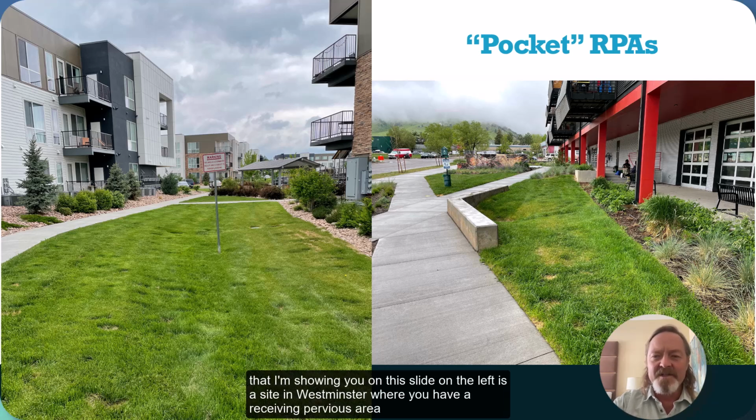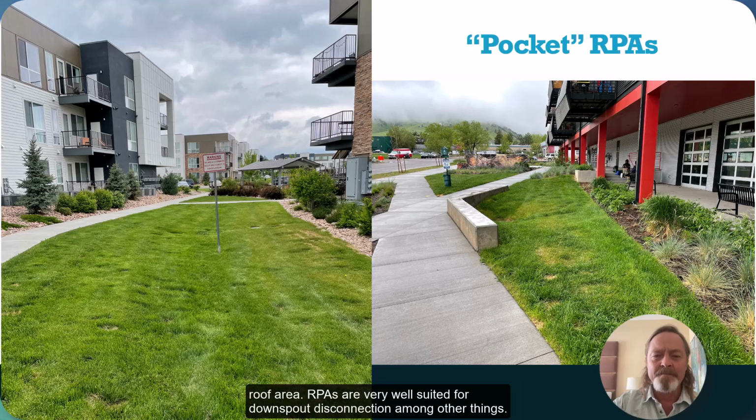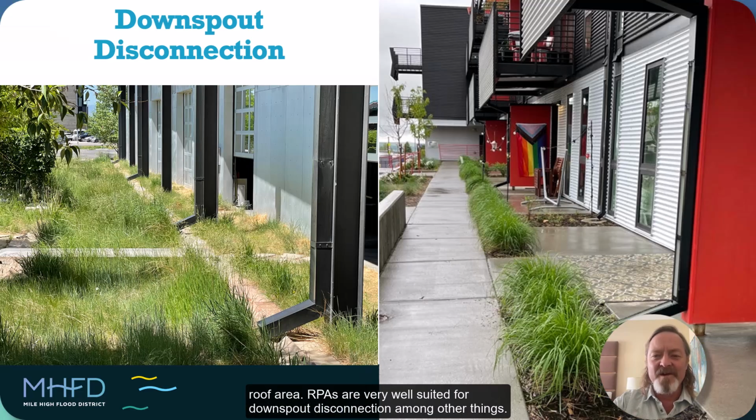The image I'm showing you on this slide on the left is a site in Westminster where you have a receiving pervious area that allows for shallow ponding and infiltration of runoff from the surrounding impervious areas. The photograph on the right is an example of a receiving pervious area that downspouts are draining to from a roof area. RPAs are very well suited for downspout disconnection, among other things.